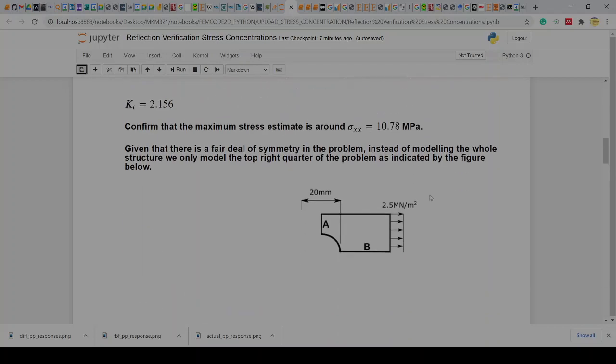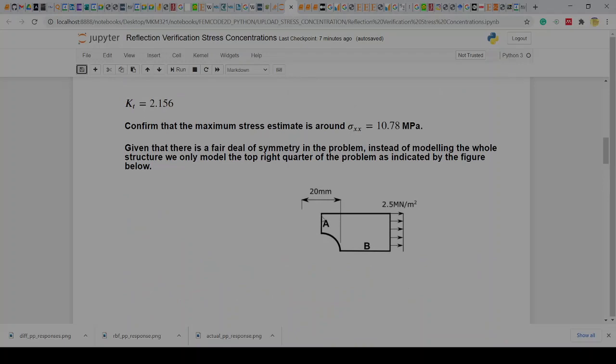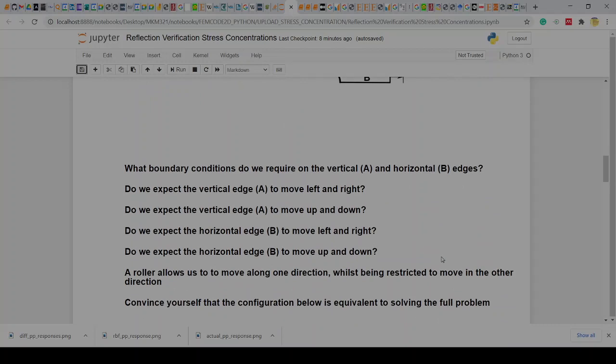Go and take each of these measures and estimate for yourself what the consistent nodal loading would look like, as well as what the boundary conditions would look like. And you can also ask yourself, if we apply rollers like this and apply rollers like this, then there are no rigid body modes left. So this thing can't rotate. It can't move left, it can't move right, because the rollers here would limit any horizontal movement, and rollers here would limit any vertical movement. And because we've got both rollers there, that limits rotation. So no rigid body modes. So that's something that would solve.